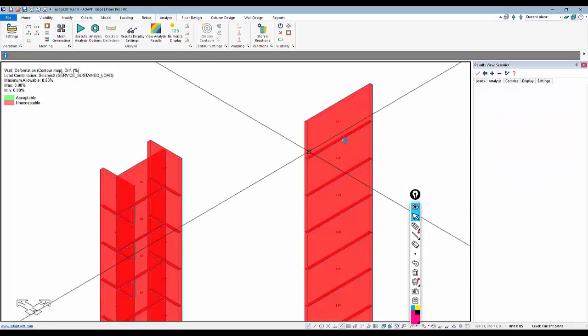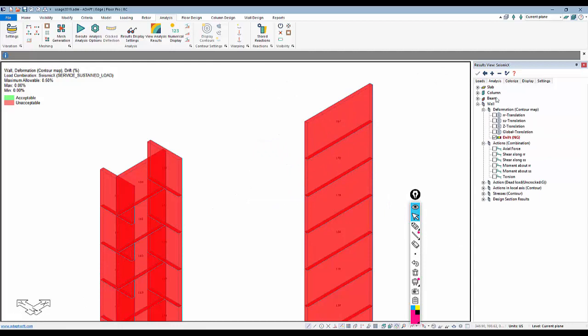Okay, that one is now done. You can see that number jump up. Now we're looking at the latest result. So remember, this drift result is actually a function of just the load combination, seismic X. So that means that it's using the latest solution for whatever usage case we ran, which is the crack 25. And we can see those numbers went from 1.04, 1.16 to 1.58, 1.67.